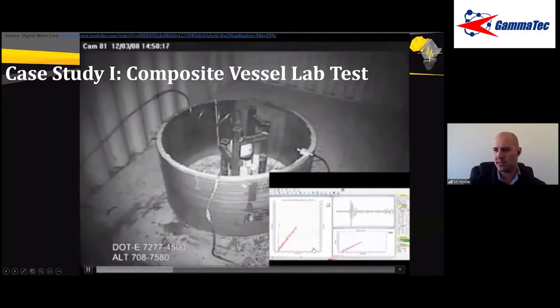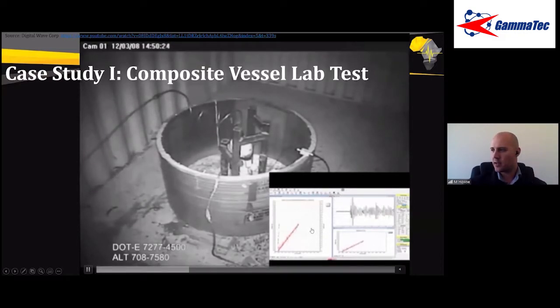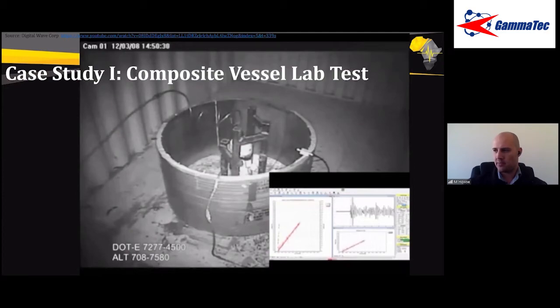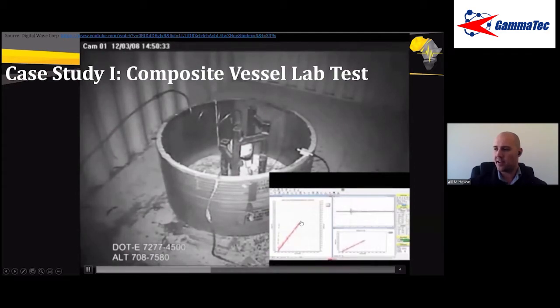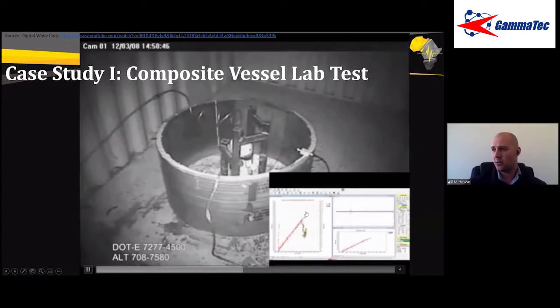So as we're pressurizing this composite material, should it begin to fail, we should expect to see some emissions starting over there. And then as the fibers in the composite material break, you should have a reduction because their load then falls to the better fibers. So you have a reduction in noise and it ramps up again. And you get this oscillation type, and that's very unique and archetypical of composite materials. So here we can see immediately, well, hang on, there's some failure happening over here.